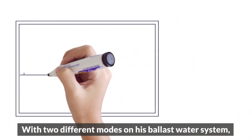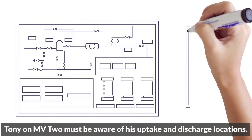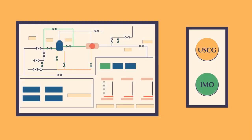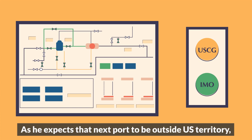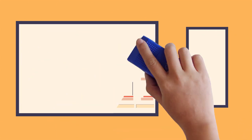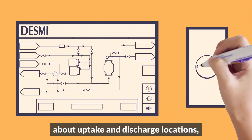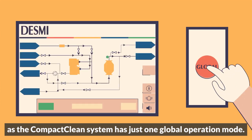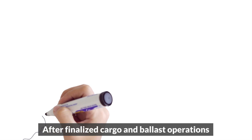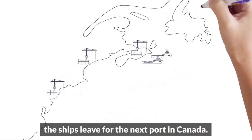With two different modes on his ballast water system, Tony on MV2 must be aware of his uptake and discharge locations. As he expects the next port to be outside US territory, he sets his ballast water management system in IMO mode. On MV1, Owen doesn't have to worry about uptake and discharge locations, as the CompactClean system has just one global operation mode. After finalised cargo and ballast operations, the ships leave for the next port in Canada.